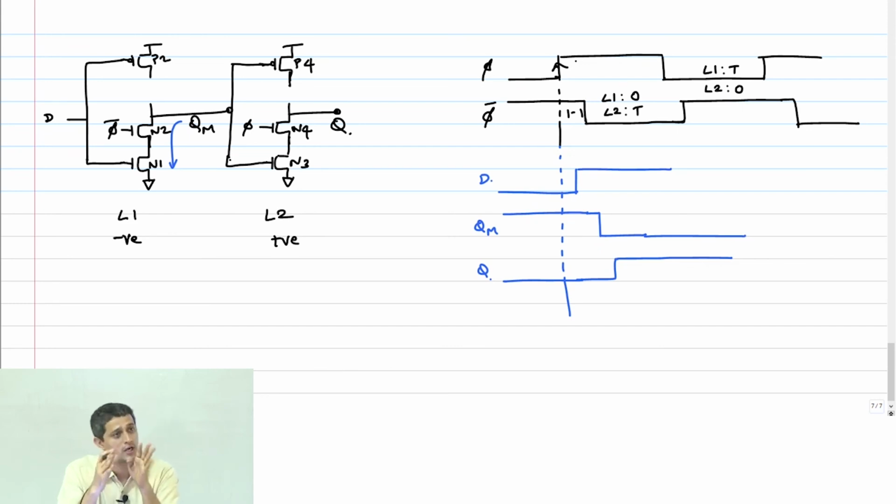Sampling edge, you can impose this condition. Worst case, let's say you designed it wrong, something happened. You just say, okay, my hold time is larger. It doesn't mean that the circuit is unusable. But if there is a violation on the non-sampling edge, then that's a race condition and it is not even fixable later. You have a big problem. You cannot impose a hold time constraint or a setup time constraint. So in this case, you just impose the condition that T hold should be greater than T overlap of 1, 1. I'm sorry.